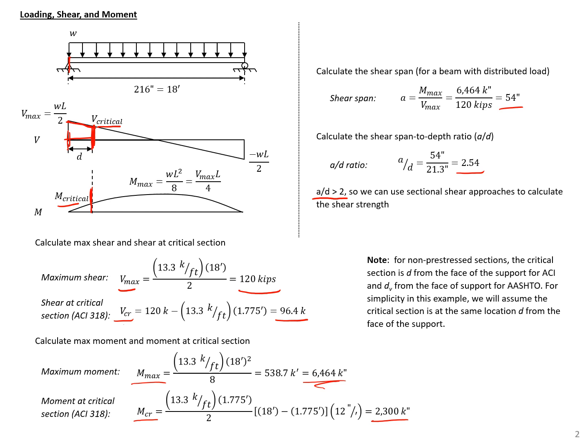If we had a shear span to depth ratio less than 2, then we need to consider this as a deep beam member, and we can use the strut and tie method in that case.